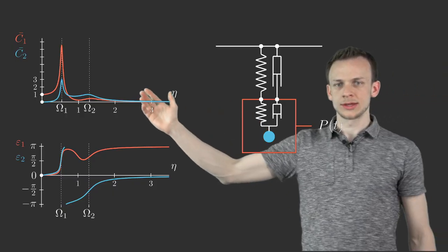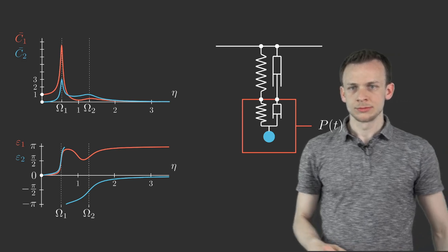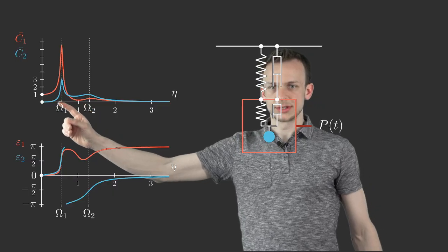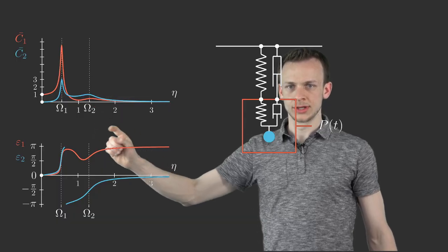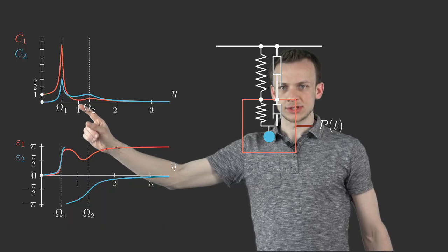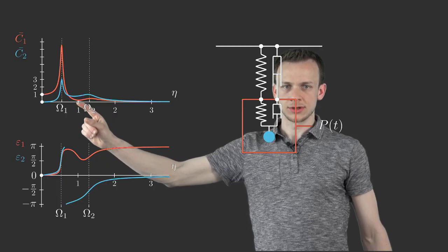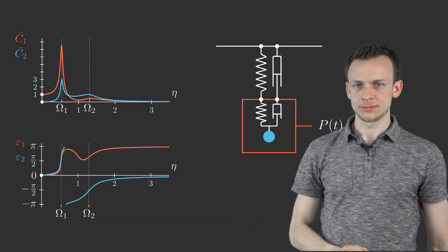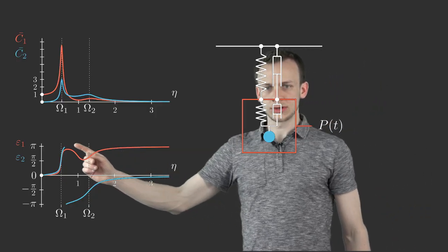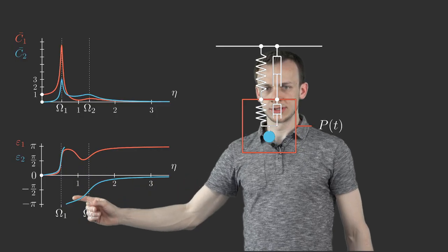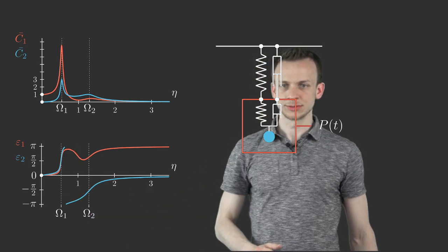And then we have a certain change of the amplitudes and of the phases. Again, we have the amplitudes for the resonant frequencies, which become quite high, not so high for the second one. And we have the characteristic frequency for the tuned mass damper, where the amplitude, the red curve of the outer mass, almost becomes zero. And we have a certain characteristic of the phase shift. Don't be confused because of the jump of the blue curve here. This is just the same value from pi to minus pi. So this is a smooth transition.